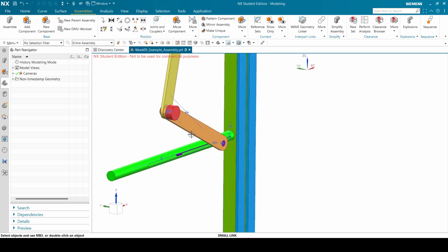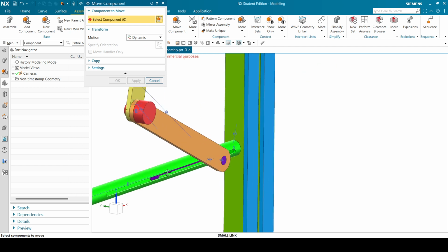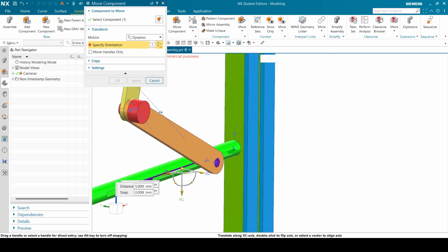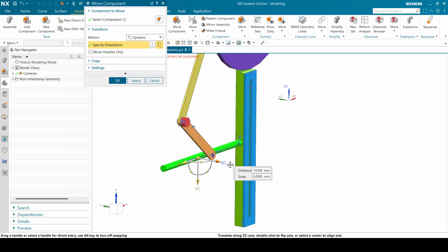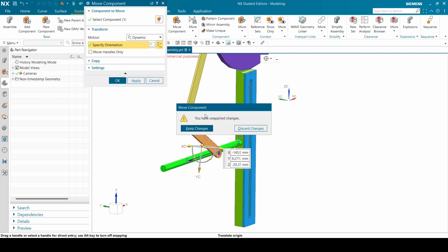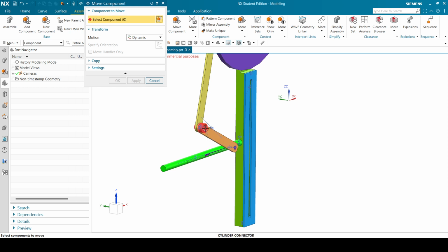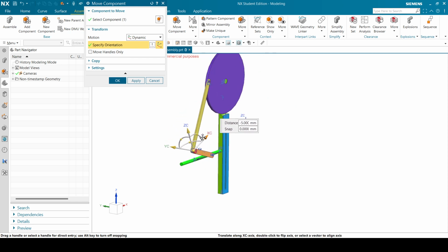So now everything looks like it's nice and aligned, but first you need to make sure that it's nice and aligned. So if I try and move this, it will still move because I haven't fixed it in place yet, or I haven't specified a constraint yet. So this still needs to be changed. But if I try to move parts in a way that they're not supposed to move, then obviously, okay, it will still move side to side. But you must always just check that your parts actually are constrained properly. So you must basically try and break your assembly. And if it won't break, well then, wonderful. Obviously that's allowed motion.